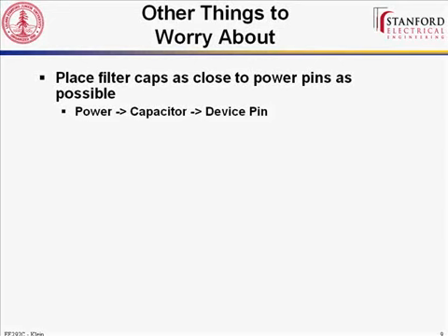So your tantalums are a little bit slower to respond, but at least they're better than having to wait for the propagation delay down a trace. Okay. So it seems that we are limited by the availability of capacitors. Yeah, so you're basically limited by capacitor technology. I have yet personally to see a reason why you would have to use tantalum and couldn't just use ceramic everywhere. There may be some reasons in some applications, but I can't think of any immediately off the top of my head.